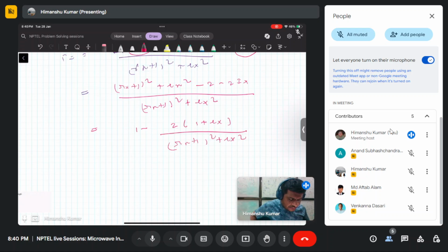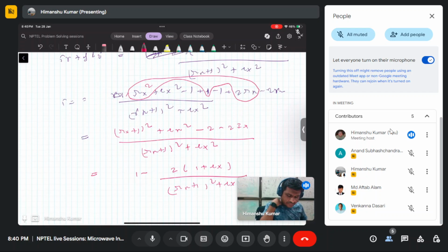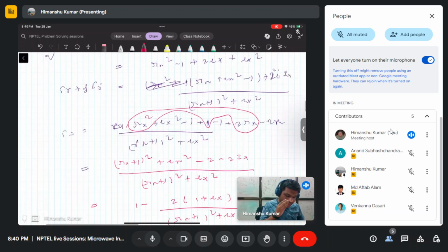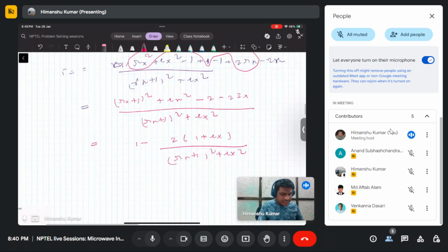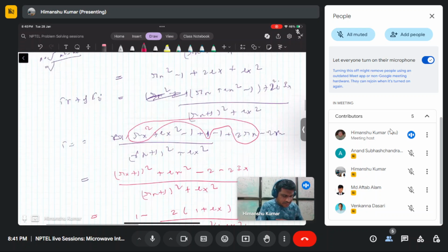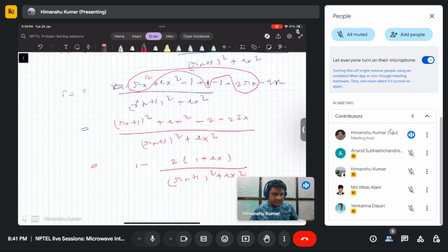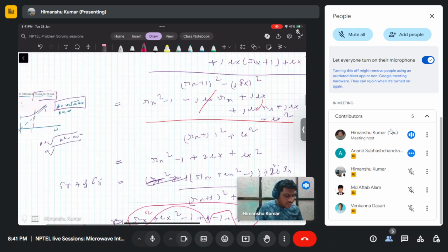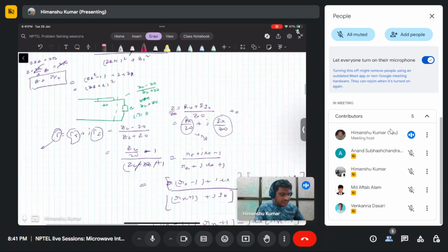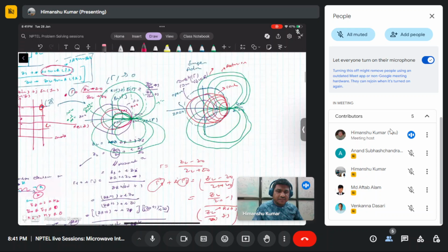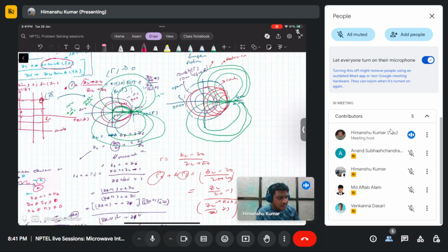So now, if you can represent this circle, the complex impedance of this part, you can write this Ix and Rx in terms of gamma R and gamma I. So basically you just transform from one plane to the other plane. If you try to solve this equation at home, you will see that there are two kinds of circles.